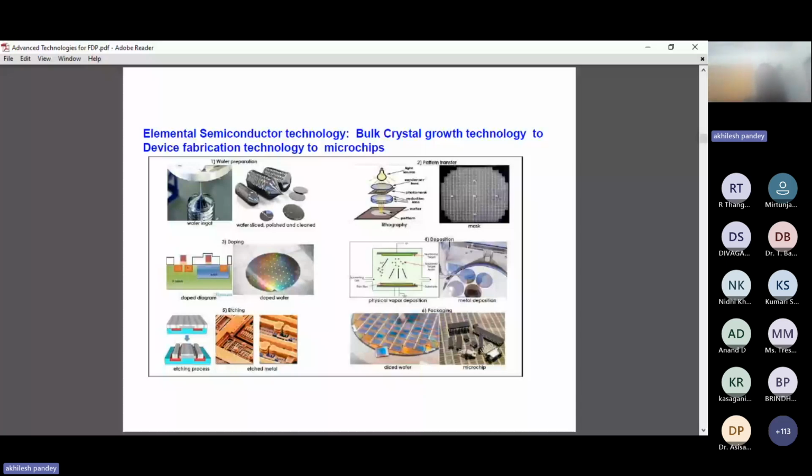For slicing, there is another technology to fabricate the silicon wafer. Several steps have to be used: shaping, then determining the orientation using an X-ray goniometer, then cutting, then polishing, then chemomechanical polishing.